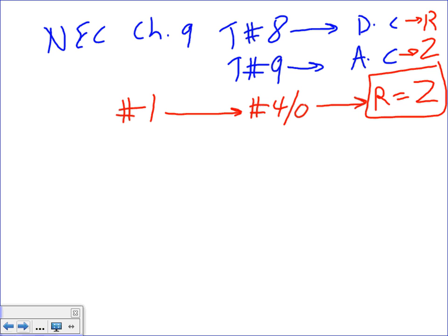That's why we always use table 8. If you look at the values of Z and the values of R from table 8 and table 9, for the most part, up to size 4 aught, they are kind of the same. So you can use either. Higher than that, you start getting into the impedance. And I don't want to go into the impedance because I leave this one to the commercial. Get into the impedance, and you start using Z.